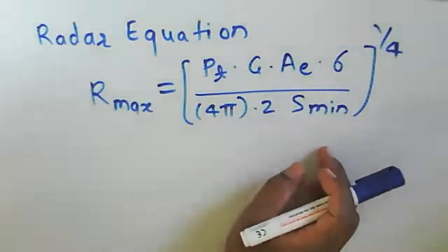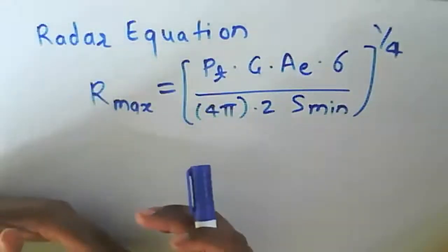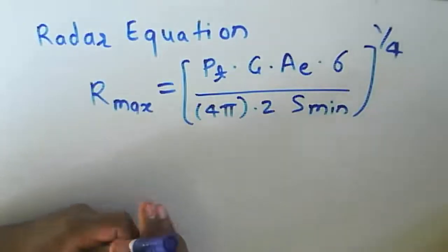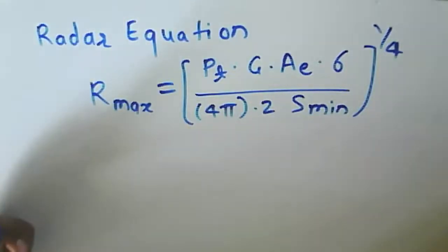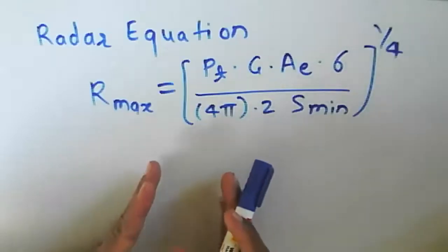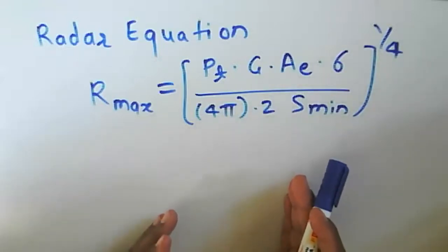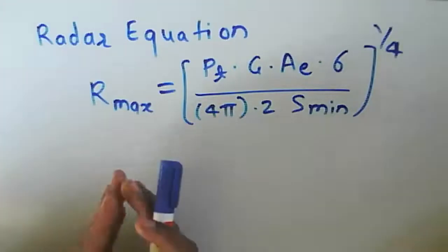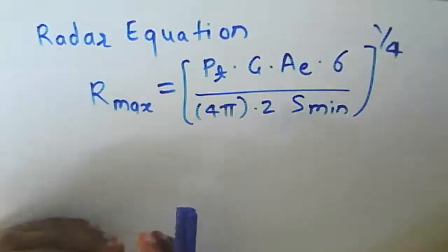For that purpose, we again need to know what the various components present at the receiver in a radar block diagram are. We have the mixer, then the IF, then the detector, and then the video amplifier. All these components belong to the envelope detector.